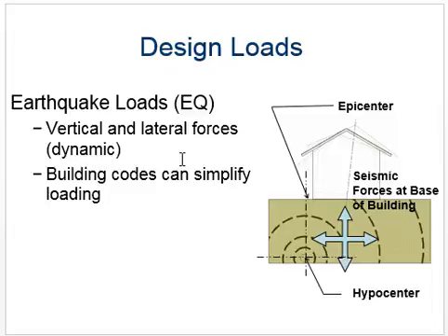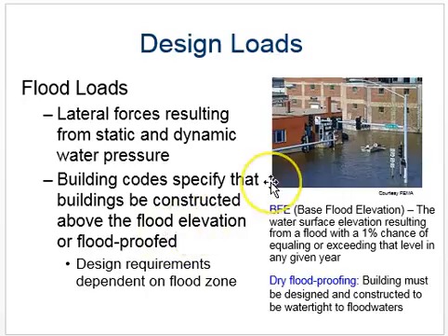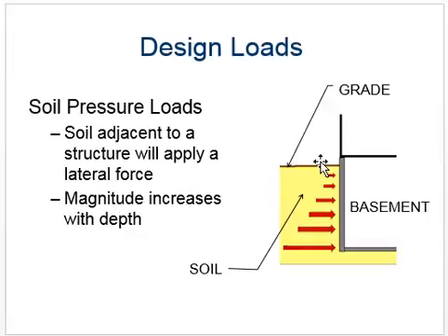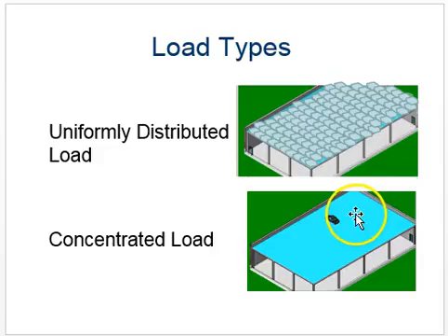Earthquake loads. They'll be different importance in different areas, but they affect our building. Flood. We've seen a lot of flooding in the last few years. It is an important factor. We don't want our building to literally be swept away if there's a flood. And design loads. If we have a basement or a part of our footing that goes below the ground, the soil is creating pressure on those underground portions, and we want to make sure that they don't cave in.